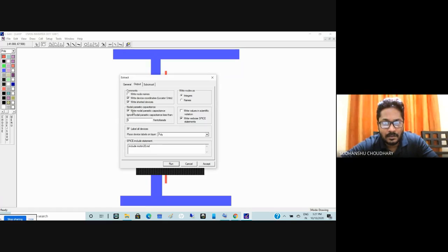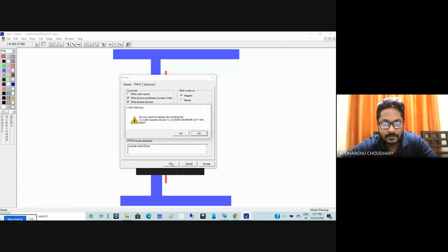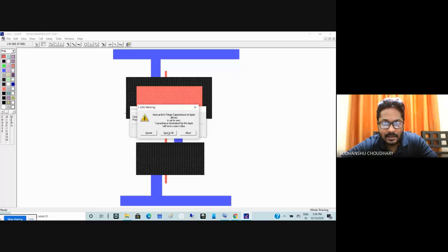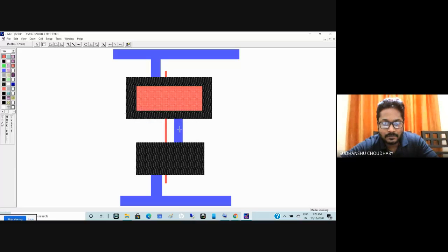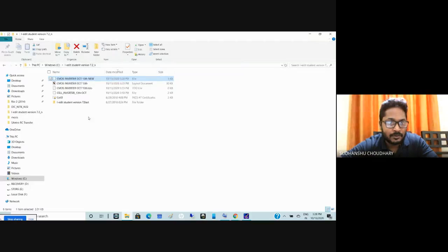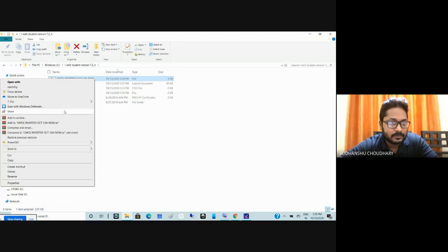Unless you select this, you will not see any parasitics. Then you say run, replace existing, yes, and then say ignore all. Then I go back again to the same file here, we refresh it and open it.